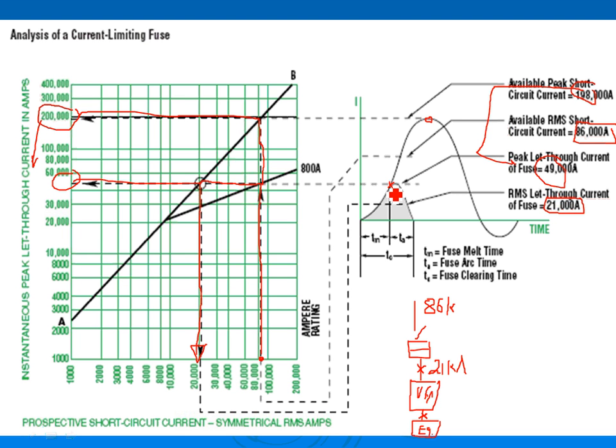When we have a ground fault or a short circuit condition, guys, what happens is the voltage goes to zero momentarily. What happens if you take phase A to phase B? Your voltage goes back to zero, you shunted them together, right? And to compensate for a voltage of zero, what happens to the current? It shoots up in the sky. And that's what pushes the energy inside your building. So they cut it faster, cut it before it starts climbing up. And that's the claim to fame for current limiting fuses, and they do work. Any question, guys, about that? Any comments?